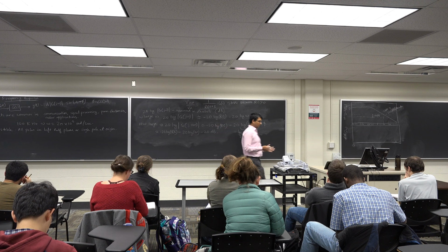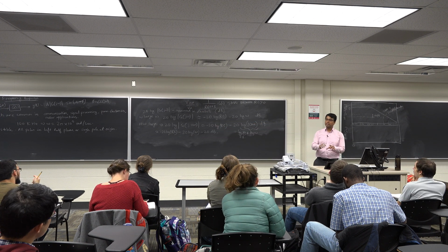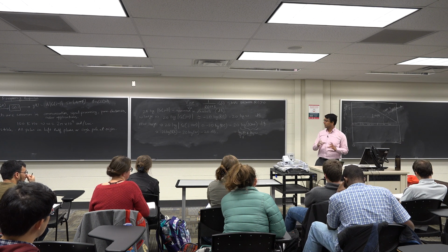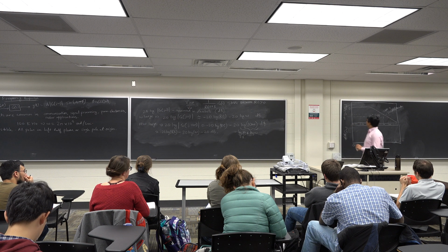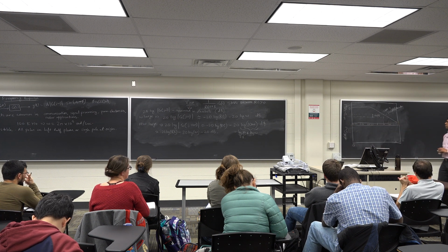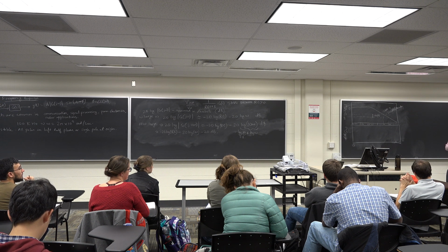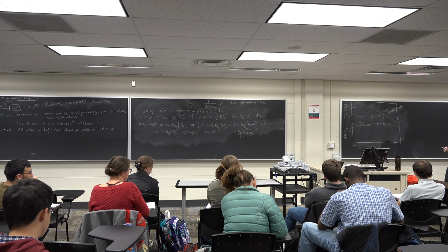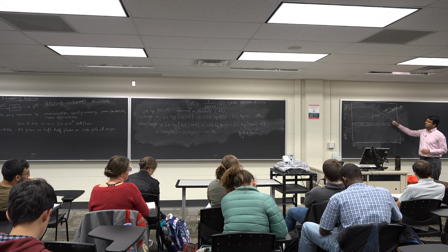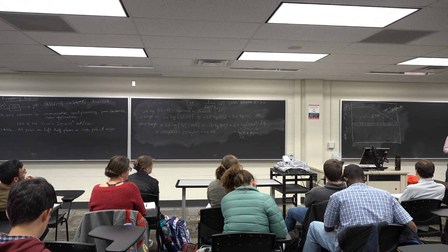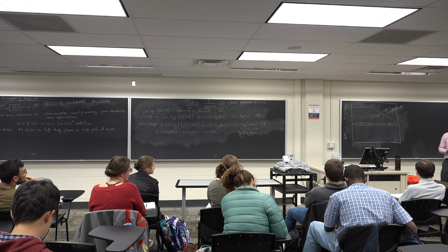And I ask you the following question. I want to know what's there in that box. What kind of circuit, what kind of system is sitting in that particular box. My question is, given an oscilloscope or a sinusoidal function generator which was available at that time, and given an unknown box, a circuit, can you plot this curve just by using these two items? You can? How would you do it? Frequency sweep and then measure response.